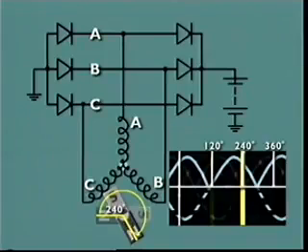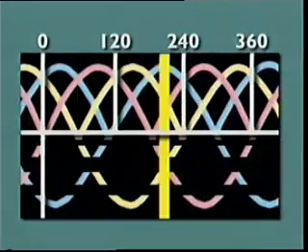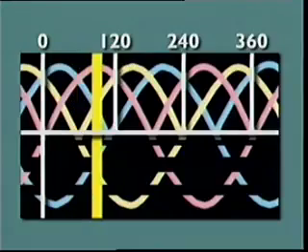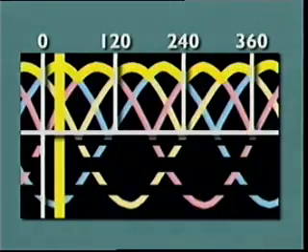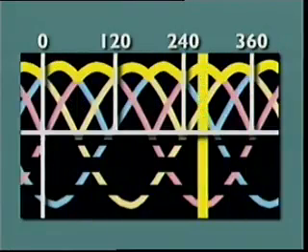The current path then is winding A at star point, winding C, positive diode C, alternator terminal B plus, battery positive terminal, battery ground, alternator ground, negative diode A, and output of winding A. As the rotor moves through its various positions, individual phase currents change in magnitude and polarity, but the output current to the battery and the electrical circuits remains unidirectional.